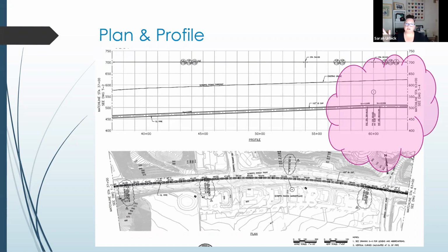We're not expecting it to vary a whole heck of a lot, but it could, because roadways are built with a 2% slope going to either side. Then we're looking at the roadway that's increasing in elevation. So if we're at 610 elevation over here, here's 620, down here is 570, 540. We know we've got some incline there. We can see that in the profile of the existing grade. Okay. So little detour, little education, little history.